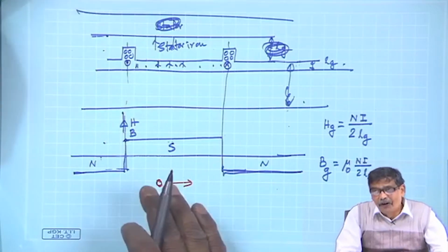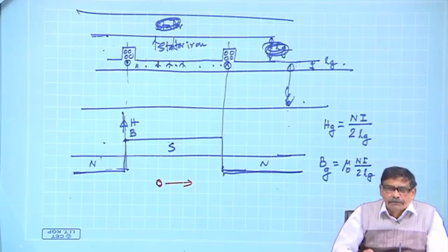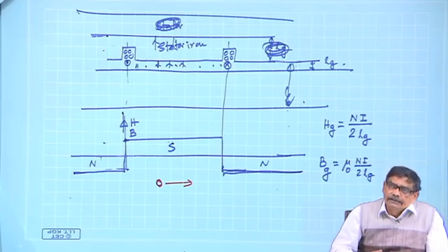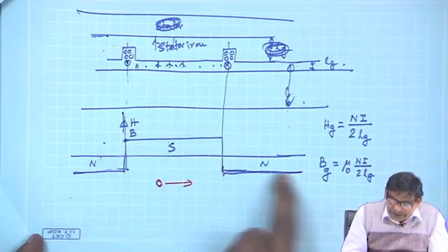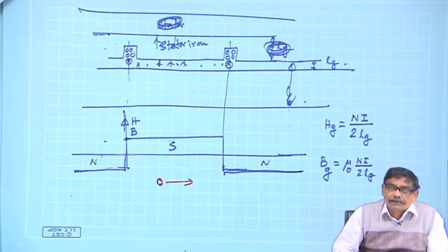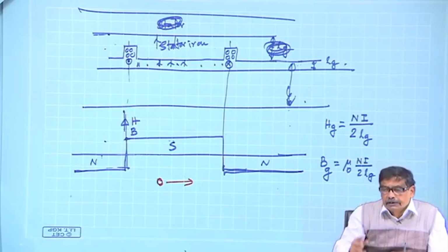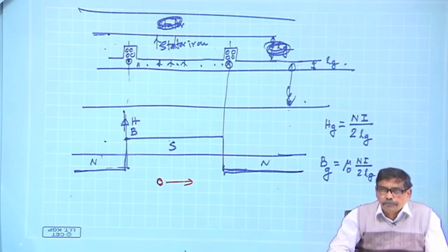But the irony of all these things is this, because by this time all of us know that the voltage available at your power point, the plug, is AC voltage. It is AC voltage no doubt, but it is not a sinusoidal voltage. Sinusoidal AC voltage, we say 220 volt 50 hertz supply. It means that it is a sinusoidally time-varying voltage with peak value 220 into root 2.